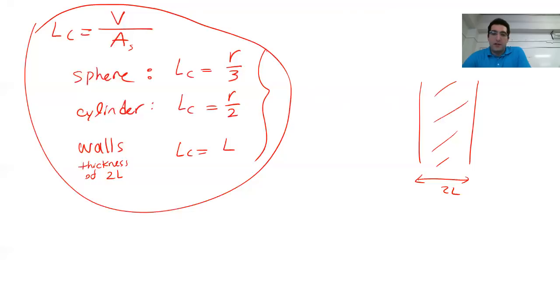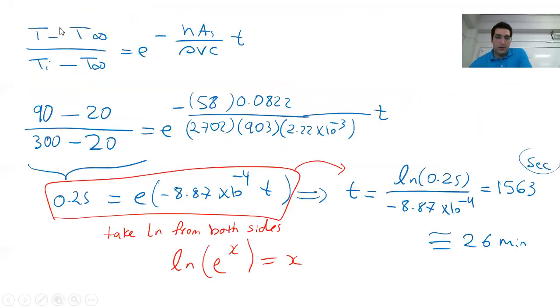So we covered transient conduction, but make sure if a problem is to be solved in transient conduction, first of all, you want to show that the Biot number is less than 0.1. So that check process is important. You have to show it. Then use the equation we talked about here to find either time, if final temperature is known, or if you want to find out after 200 seconds what would be the temperature, you can find T.